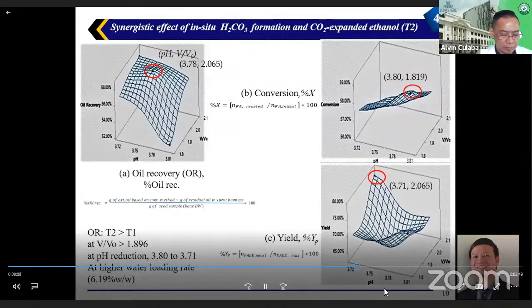Besides, the water in the feed will reduce the equilibrium conversion and influence phase behavior. So chemical equilibrium and phase equilibrium effects could occur respectively. Furthermore, when more water is added, the vapor portion increases and the water in the liquid phase reduces, which promotes enhanced volume expansion. But unfortunately, this does not warrant an increase of conversion nor of yield.